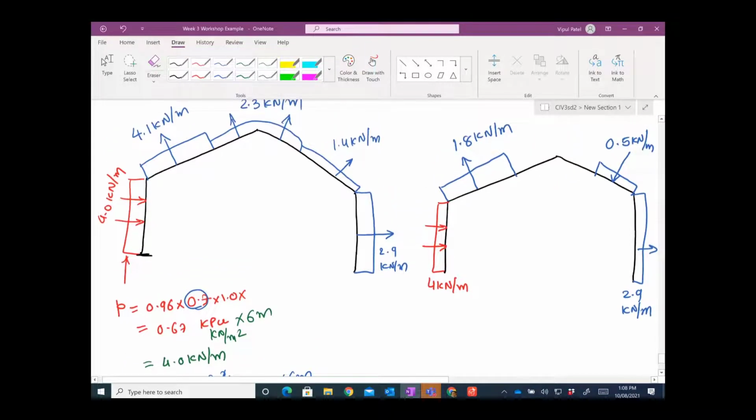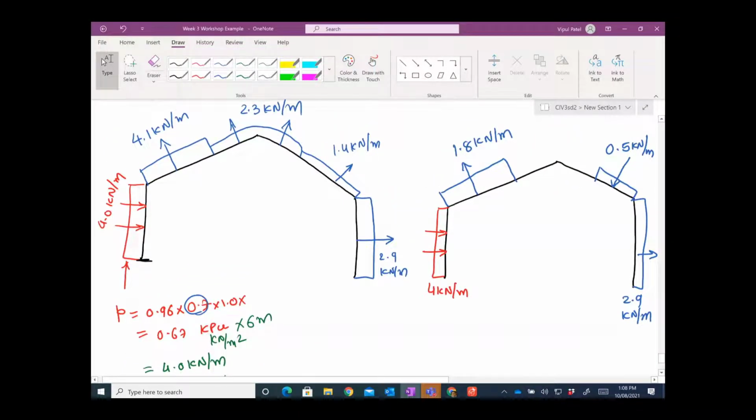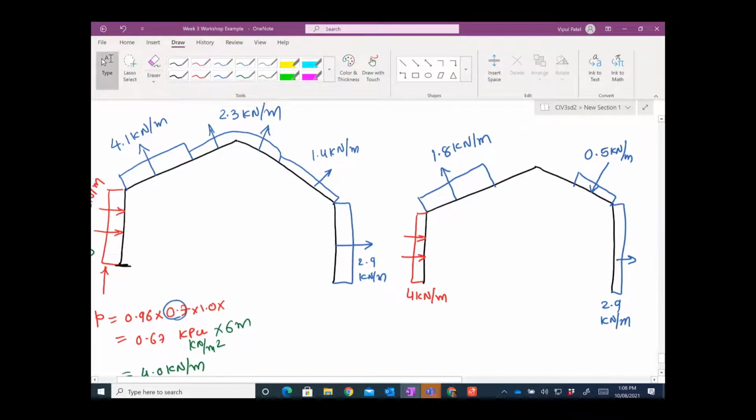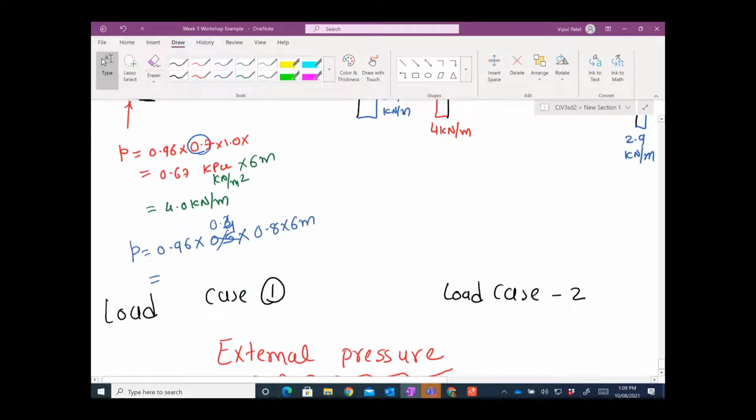You can see there's a red one. In all other ways you have negative pressures, and you can see this when the wind hits. And by the way, wind is coming from here. Okay, wind is coming from here, it pushes the wall, all other walls they will pull. Okay, except there is this one, I can put red one, sorry. So red one. All right, so we are done with those.